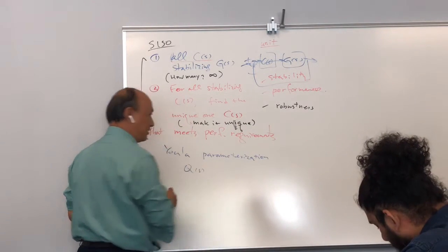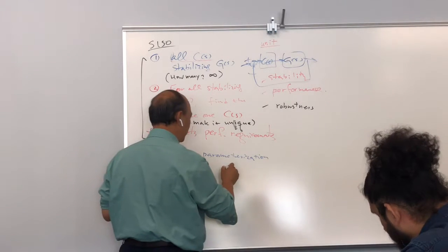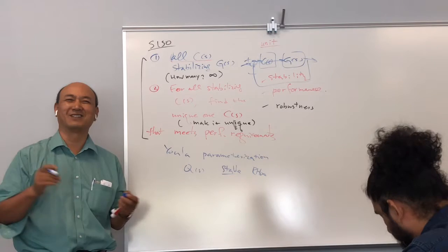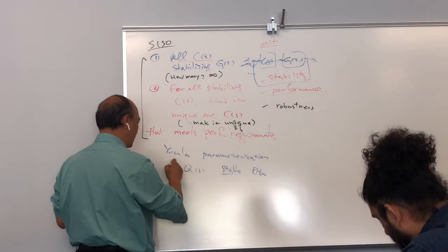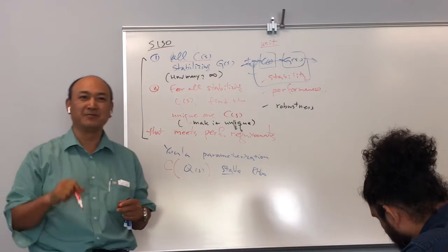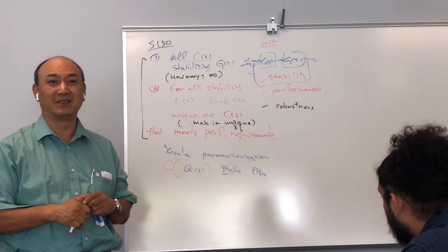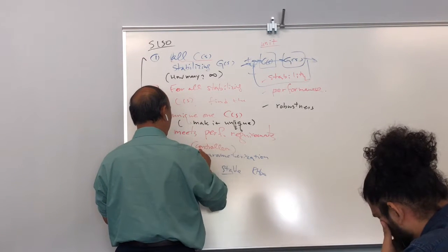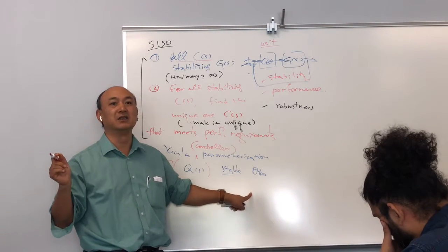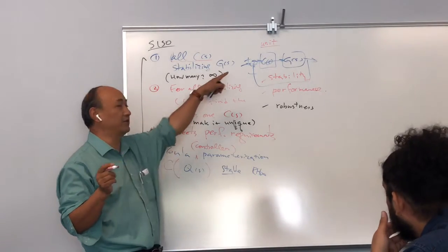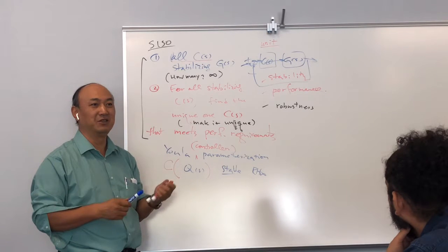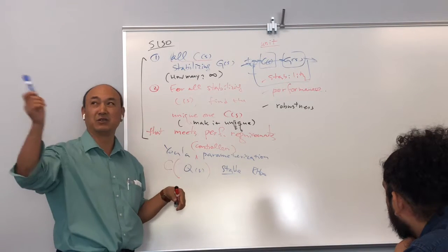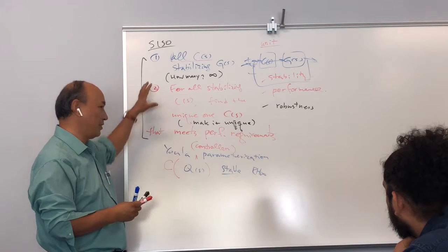Say for any Q of S that is stable, let's say in RH infinity, a stable rational transfer function or filter, okay? If I can somehow write my controller expressed in this Q of S, parameterized by that, that would be nice. This is called parameterization, so Youla parameterization, we should say Youla controller parameterization. I express my controller in terms of another stable family. Any of these will make the C qualified for stabilizing that. How to do that? Do you guys know? I will leave this one to next week. I will leave this to next Wednesday's lecture after the mu synthesis, because the next chapter will be controller parameterization.